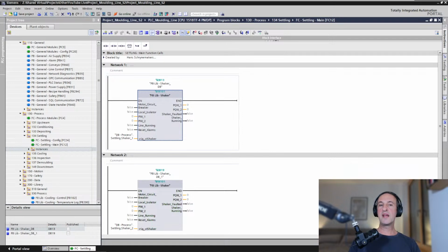That's really something. I used to be all in for multi instances because it keeps your application smaller, with fewer DBs and fewer blocks, more neat and streamlined. But if you're doing a lot of commissioning like I do, and you work a lot online, including remote work where I go online with a customer through a remote connection, then the single instances definitely have some major advantages as well.